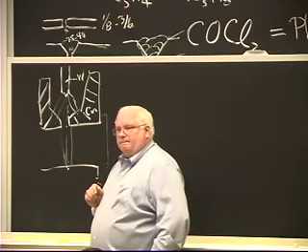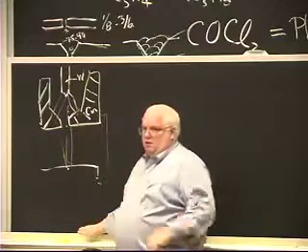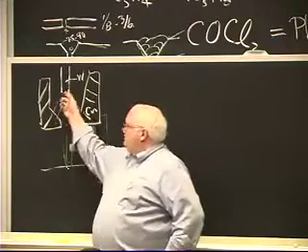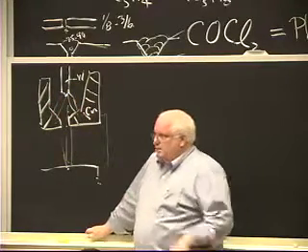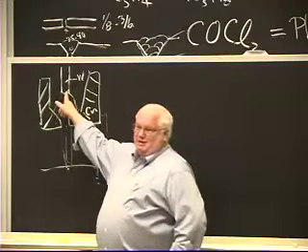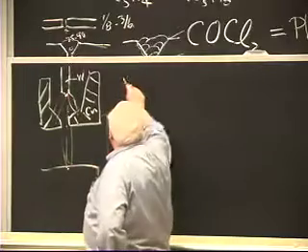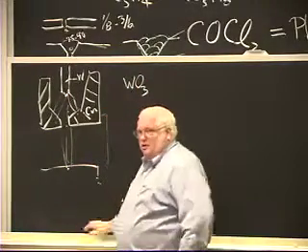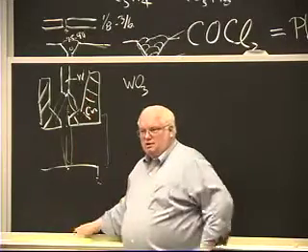Yeah? Is there gas or is there oxygen that's being fueled through there? Well, ordinarily it was originally pure argon or argon helium. Argon helium is not so good because the helium starts to melt the stuff up in here. So usually they would use argon, but about 10, 12 years ago, they developed something. Tungsten is not good in air because it forms WO3 oxide, which is a white smoke that comes off at 1,000 degrees centigrade. And you just see white smoke come shooting out of this, and after a few seconds you won't have a tungsten electrode anymore.